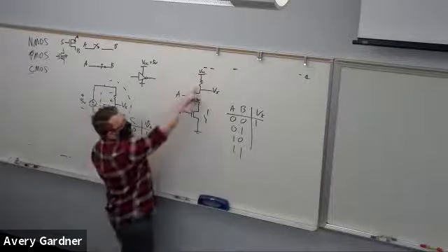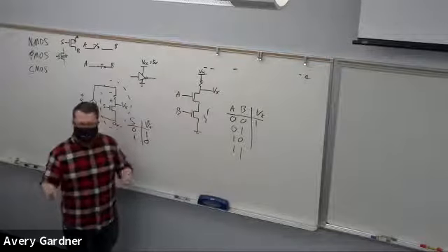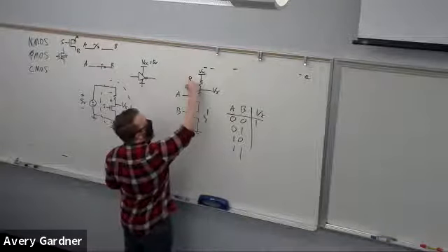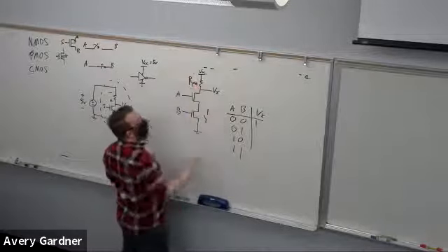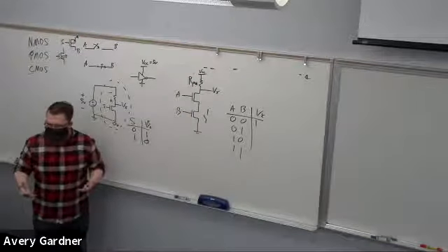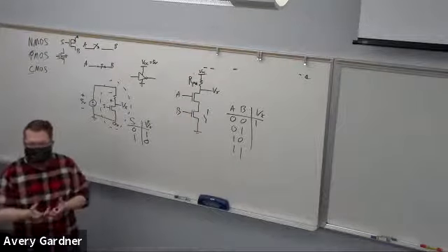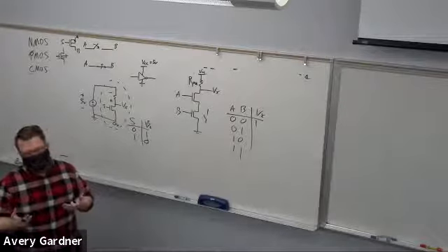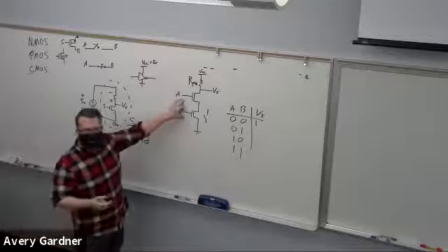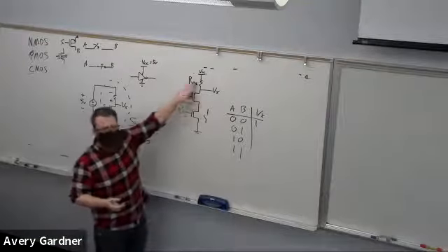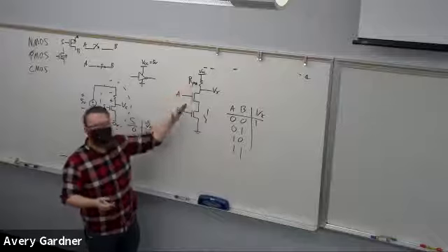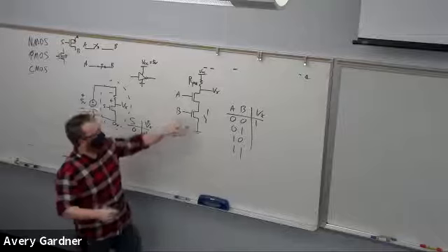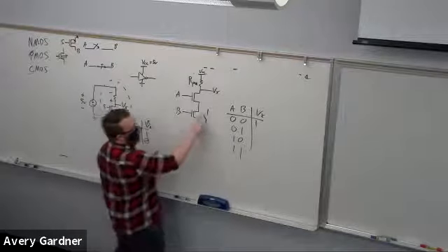We call this resistor a pull-up resistor. You will see me write it occasionally as RPU, R pull-up. What it's doing is, if there's not something stronger pulling it down, it's pulling it up to on. These switches override that resistor because they have no resistance, so they're able to sink a bunch of current and pull it to 0. But they're both broken.